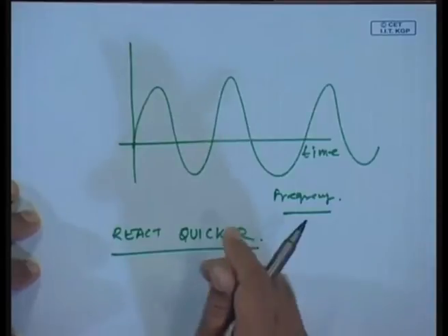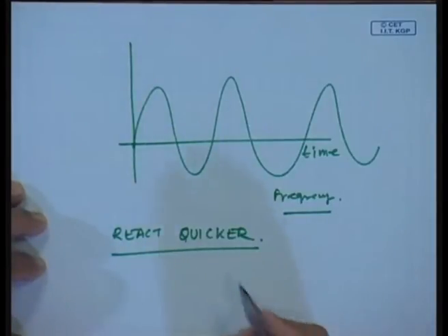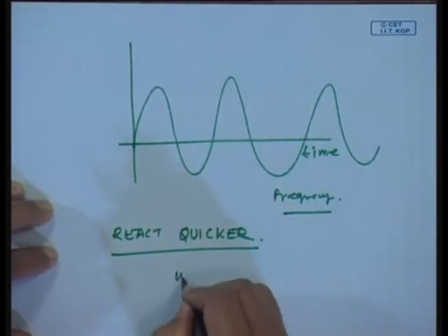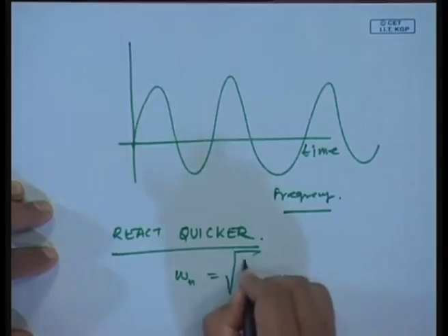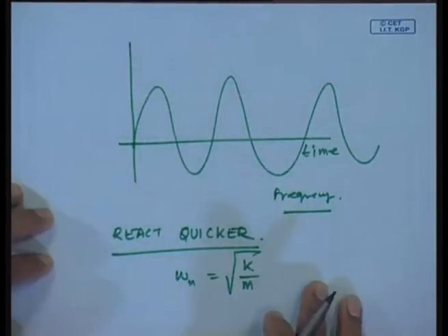because of the fact that every mechanical transducer has inertia, has stiffness, has a natural frequency, and if you recall, this natural frequency is nothing but stiffness by mass. If mass is low, then natural frequency is high. Okay. So, if I want a very sensitive equipment in terms of very fast response, its mass has to be less. I will give you another related example.